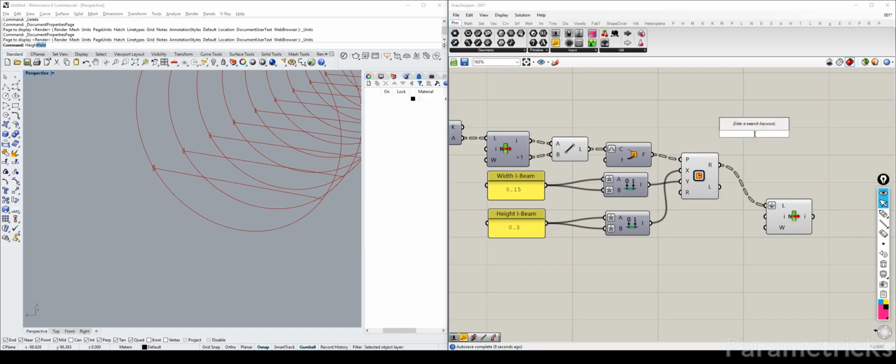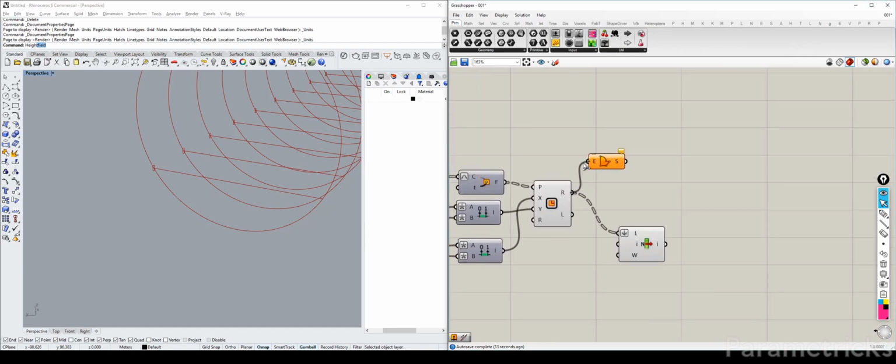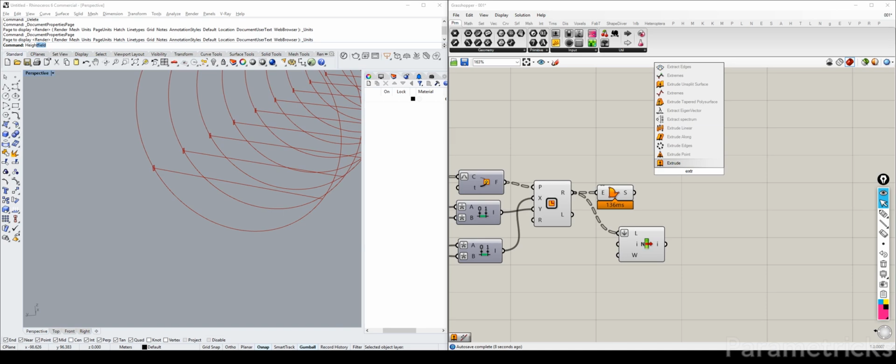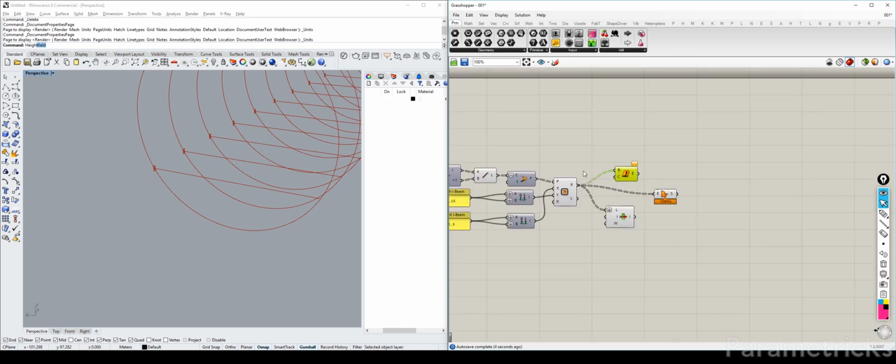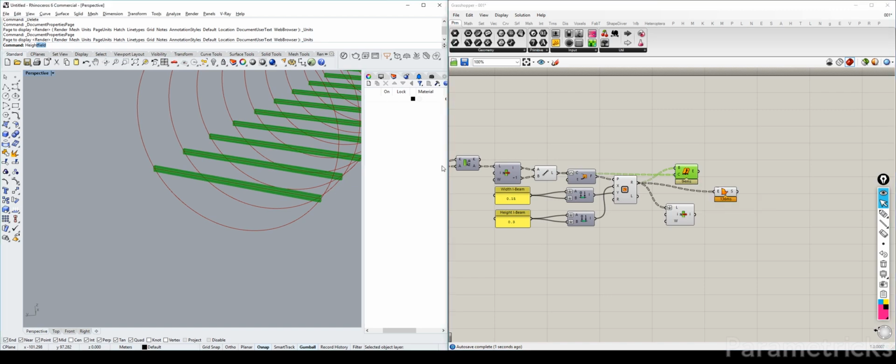Okay. The next one, what we can do is we can just boundary surface this part. 50-60% of our script already, and extrude. The direction it should extrude. Actually, we can say extrude along curve. Maybe that will help. Extrude along curve. The poly surface to extrude, which is this one. Actually, that one. Because we just need to insert profile, and the lines are these.